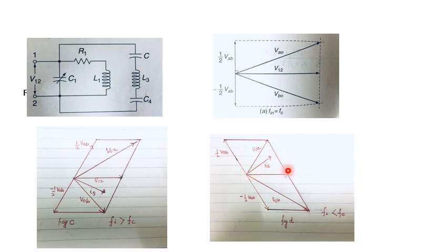that is, the secondary current will lead the primary voltage. Hence the vector half VAB will shift in the anti-clockwise direction, or the angle between half VAB and V12 will be slightly increased, and the angle between minus half VAB and V12 will be slightly decreased.